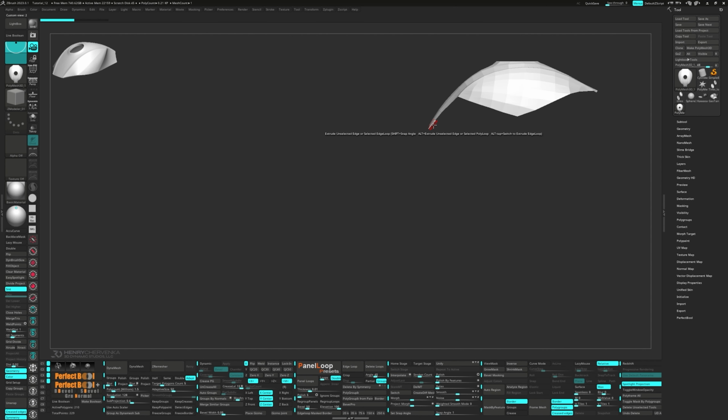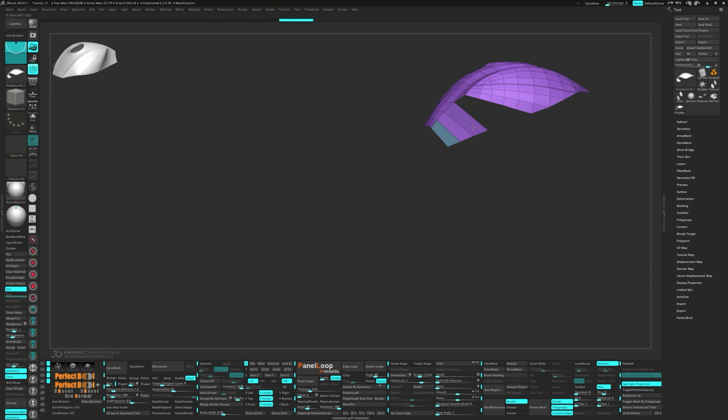From the side view, let's start extruding out those edges. On the fourth edge, extrude it just a little before it snaps to any point. In point action, choose Stitch. Then we can weld the points together to achieve the angle we need.